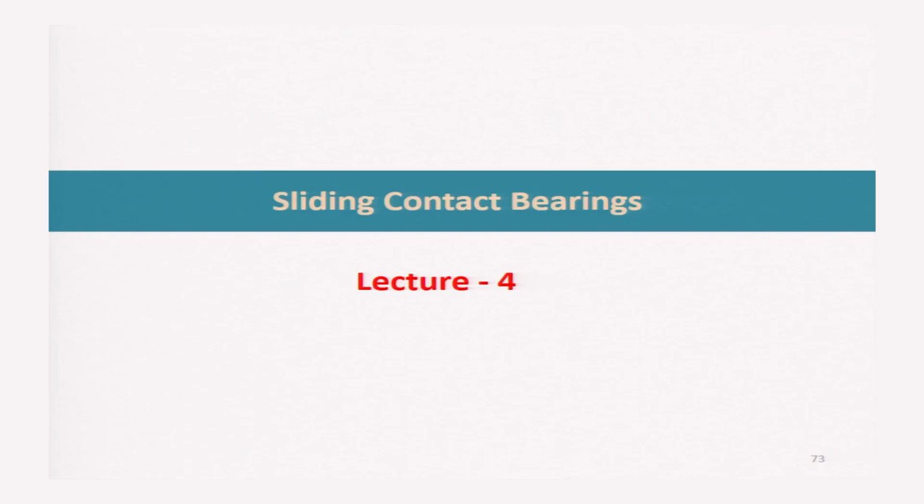Till this lecture, that is, in lectures 1, 2 and 3, we studied the introduction to bearings, different types of bearings, and then the details of the sliding contact bearing: its nomenclature, its working principle, generation of hydrodynamic pressure, and mathematical modeling for determination of the pressure profile which develops in the clearance space of a hydrodynamic bearing. That was determined till now.